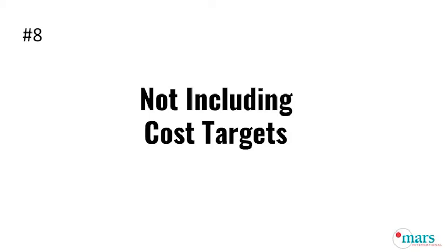Conversely, if we know that this is a high volume product, if you're going to be making millions of these things, then we may not use a microprocessor at all, or we'll go with a much simpler microprocessor and shift some other stuff to keep the product cost as low as possible, some custom chips or whatever, FPGAs. We have to keep the product cost as low as possible, even if that's going to double our upfront engineering cost, because ultimately it's going to pay for itself, because you're making so many of these things. So understanding the cost targets and the quantity targets is really important, and not looking at those is going to be a mistake.